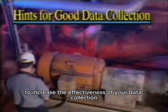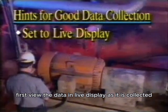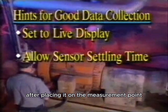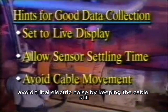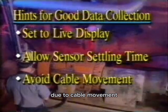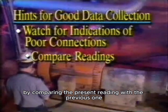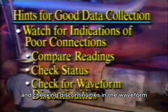To increase the effectiveness of your data collection, follow these helpful hints. First, view the data in live display as it is collected. Secondly, be sure to allow settling time for the sensor after placing it on the measurement point. Third, avoid triboelectric noise by keeping the cable still. This will help avoid the ski slope on data due to cable movement. Last, check for loose connections or bad cabling by comparing the present reading with the previous one, checking for the bad reading message, and checking discontinuities in the waveform.